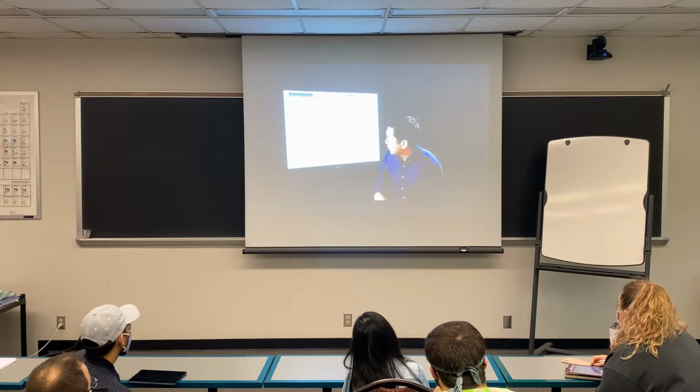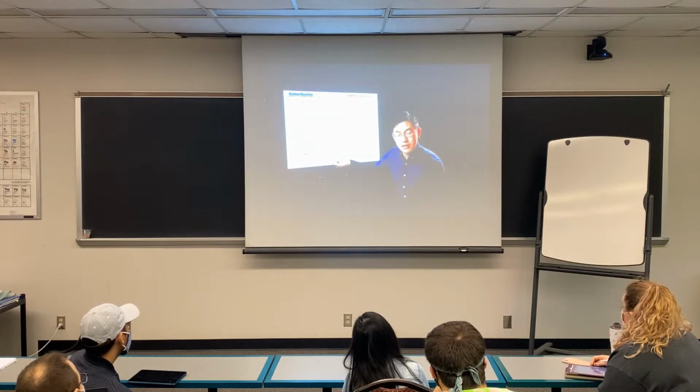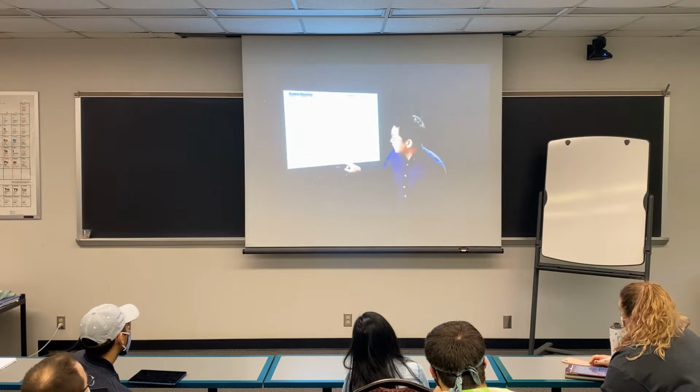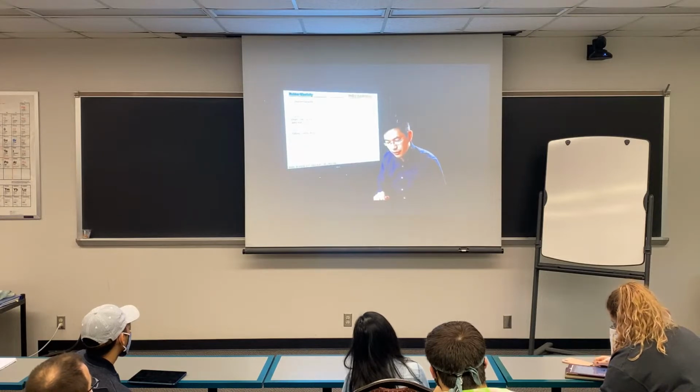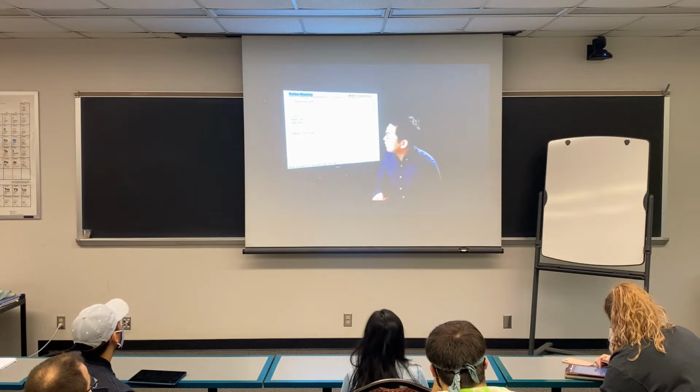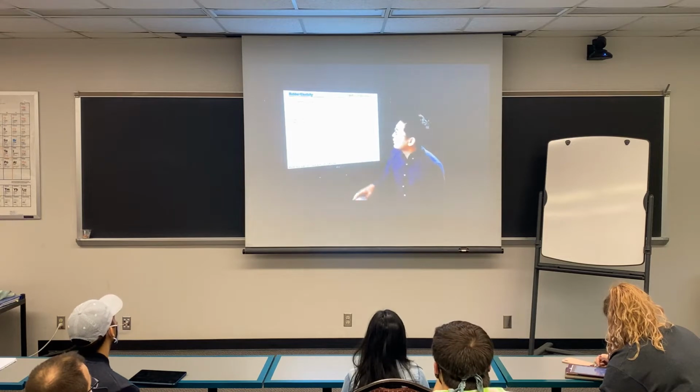Last is the number of elastically effective strands per unit volume, which is given by this. This is pretty easy to fix, and all we need to do is get a real effective strand count, okay, not just an apparent effective one. You can back calculate based on modulus what is effective. So first, let's see what assumption we can address.